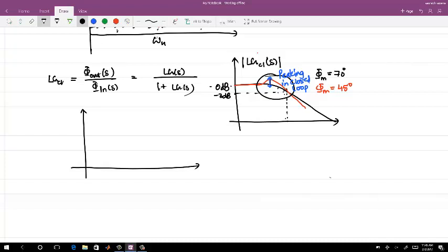So I was saying, how do you get omega u? There are two main noise sources I'm talking about right now. One is the charge pump noise. The charge pump noise is at the PFD input, so you can refer it to the input. The noise transfer function for charge pump noise, sorry, this is pretty bad, is low pass, like this.